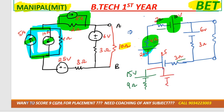It would be 6 volt and 3 ohm, and this one the same. Now after this, what can we do? Tell me. We got this value: 6 volt, 3 ohm, 9 volt and 15. Tell me what we can do further. Whenever they say source transformation, we have to use only source transformation. We can't use mesh analysis, we can't use nodal analysis.